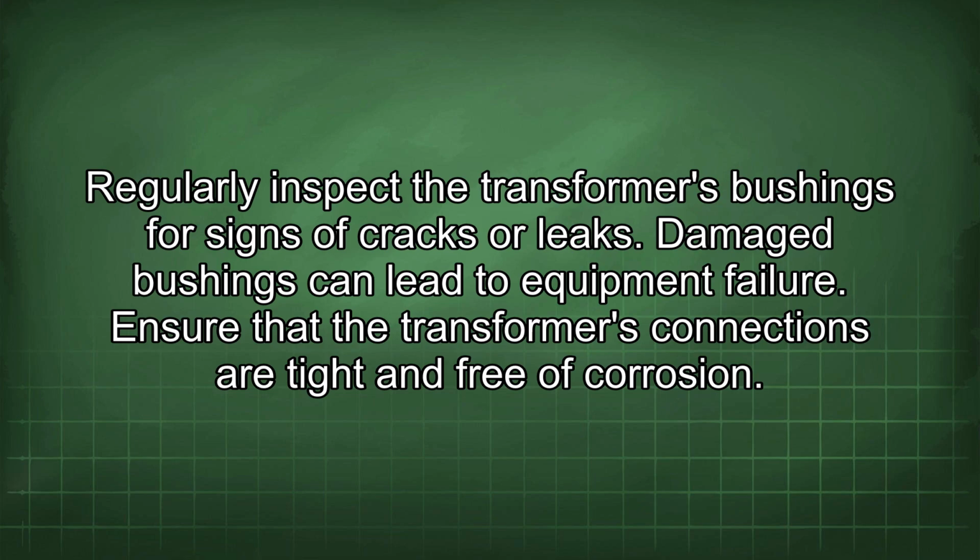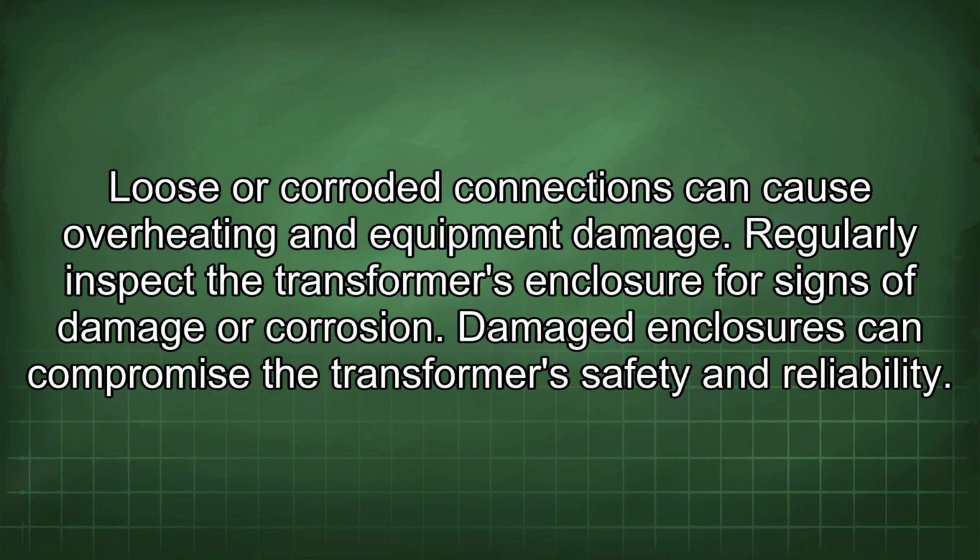Ensure that the transformer's connections are tight and free of corrosion. Loose or corroded connections can cause overheating and equipment damage. Regularly inspect the transformer's enclosure for signs of damage or corrosion. Damaged enclosures can compromise the transformer's safety and reliability.